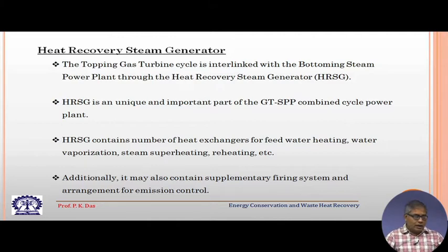Additionally, there could be a supplementary firing system, and there could be arrangement for emission control, and obviously there could be some louvers and pipeline connections. It is basically a duct. So, there could be proper connections, etc., and control mechanisms. So, all these things are there. This additional firing is one important feature, and in many cases the HRSG will have additional firing. We will elaborate on them.